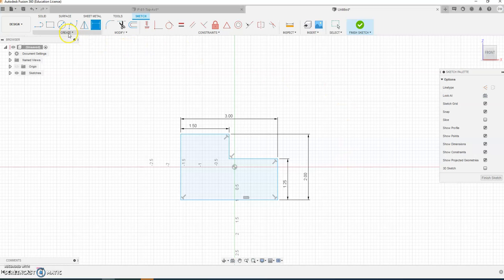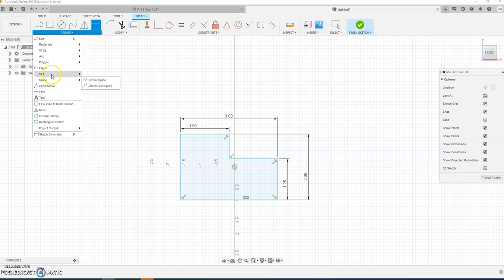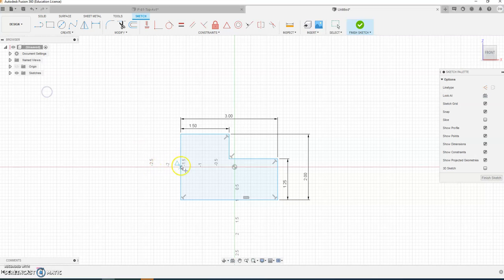Looks pretty good. What we need to do now is go ahead and create our points. Put a point in on the midpoint of this side on the right, or sorry, on the left, and the midpoint of the line on the bottom. Typically, I like to constrain the top and the right side with those midpoints, but this drawing is not possible, so you do it on these two sides and it's just as good. We're going to go ahead and then use our horizontal and vertical constraint and constrain that to our origin there, and this one to our origin here.